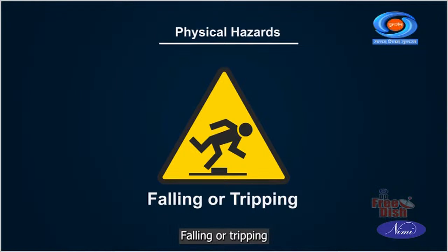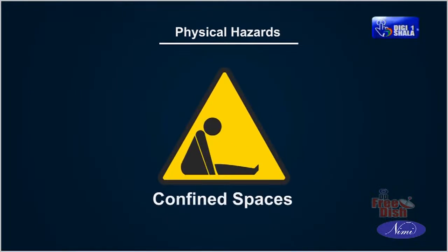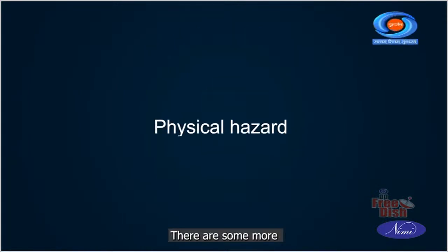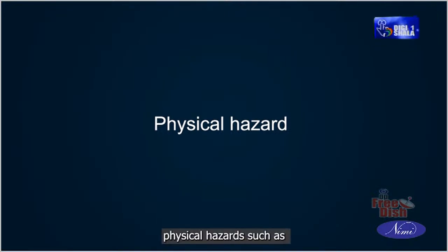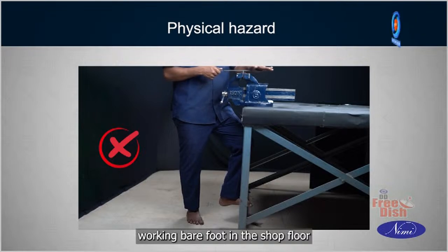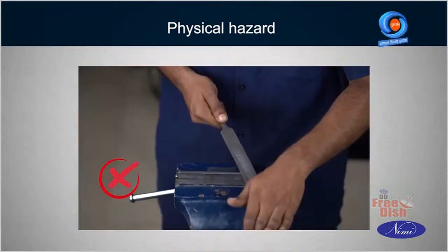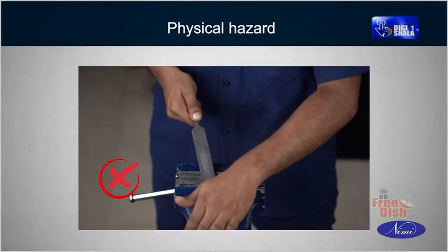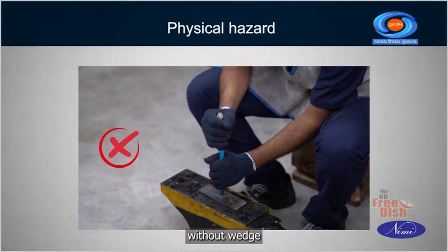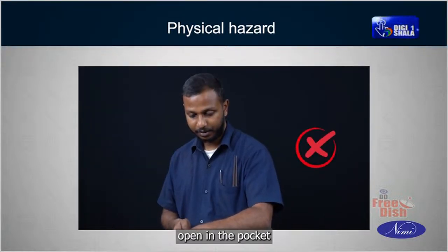falling or tripping, confined spaces, electric shock. There are some more physical hazards such as working barefoot in the shop floor, using a file without a handle, striking on a chisel head with a ball-peen hammer without wedge, keeping a scriber with the sharp edge open in the pocket,